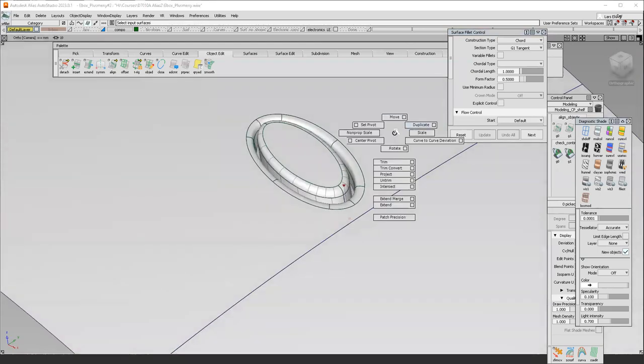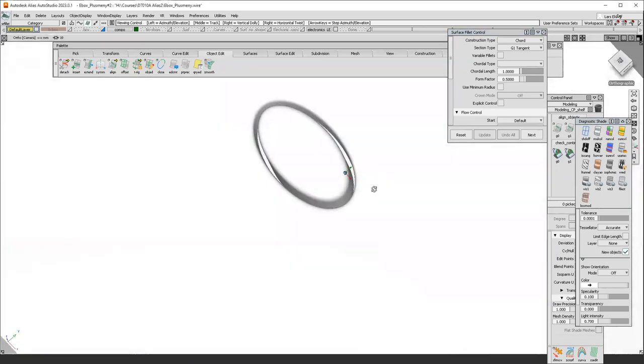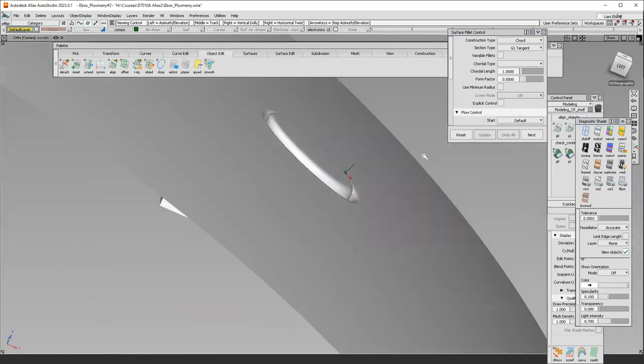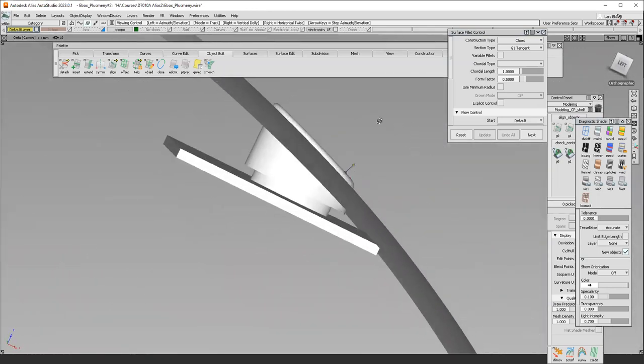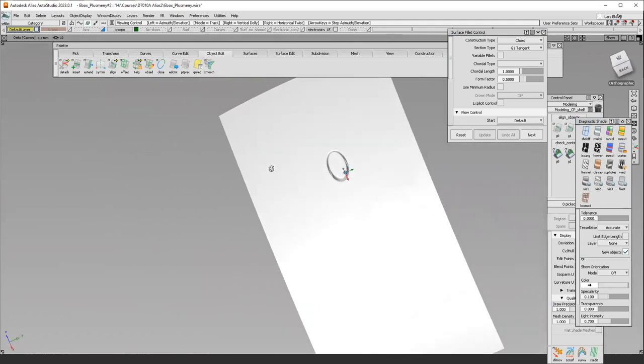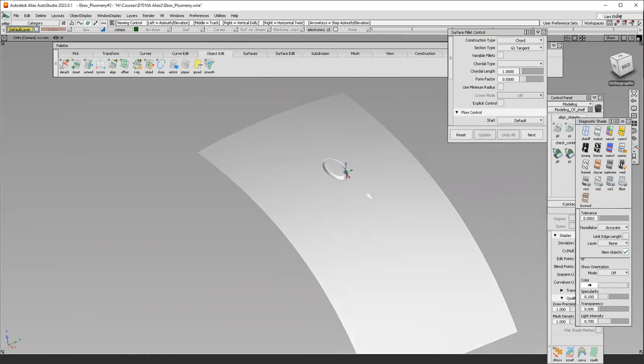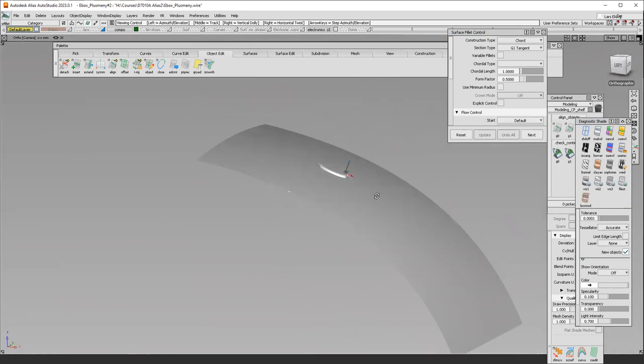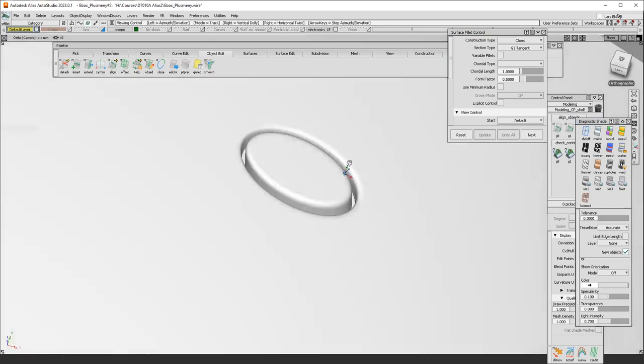So if we get rid of the model again and have a look, we have quite a nice snug fit button lowered into our casing. So this is an alternate way of creating things sticking out from a plastic cover with a draft angle and with a tight fit.